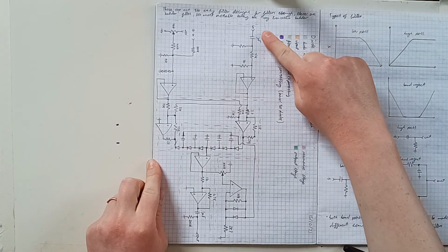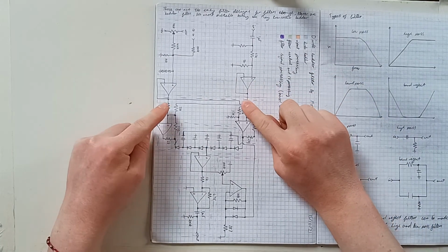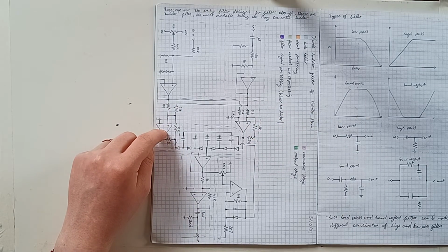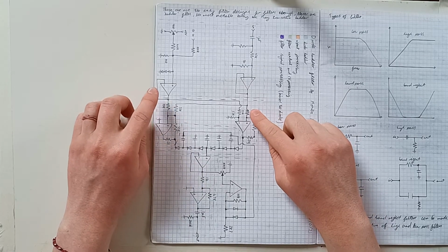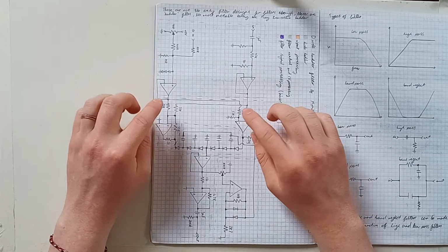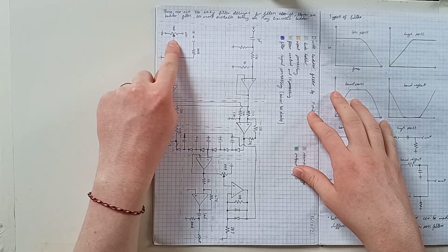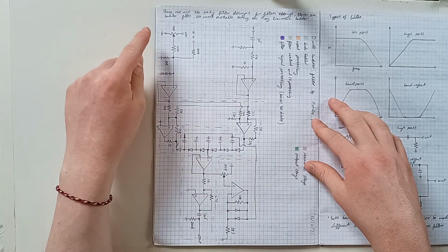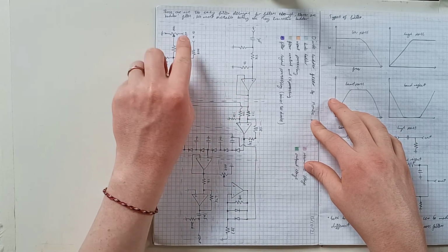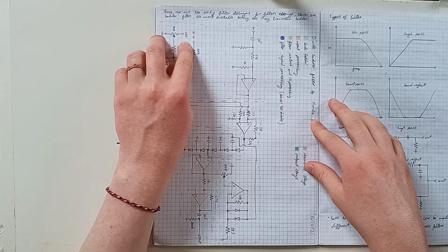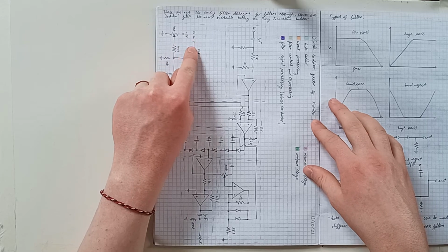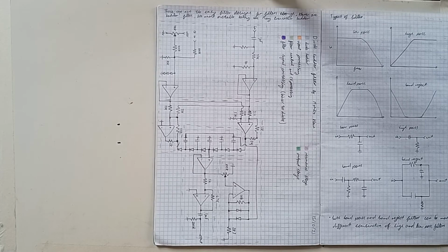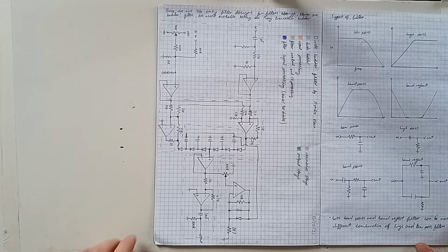You have your input signal coming in over here, where it is then split into two different op amps, which are set up in a way to add an offset voltage from one single supply, which you can adjust the actual voltage you are applying to. So that's just set up between plus and minus 12 volts on a potentiometer. And then you can also very easily add an input signal to also control the filter. So that could just be any other oscillation.